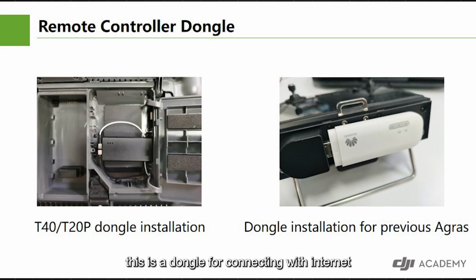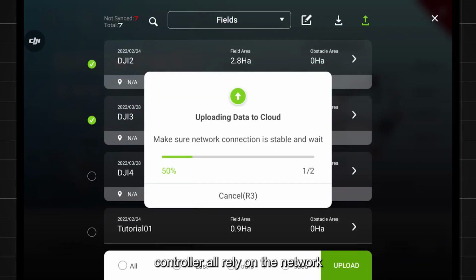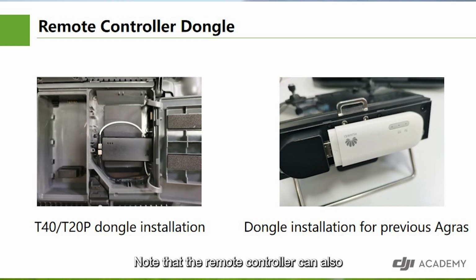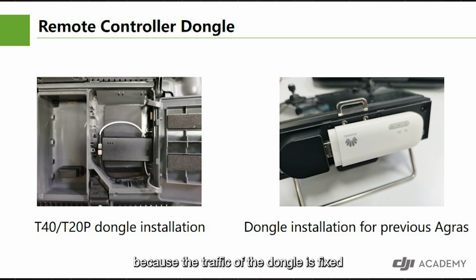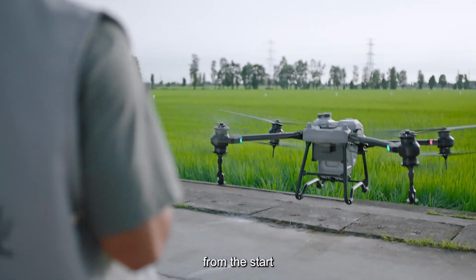This is a dongle for connecting with internet after inserting a SIM card. It should be noted that the field download, upload, and the upload of operating tasks in the remote controller all rely on the network. Note that the remote controller can also be connected to the internet by Wi-Fi. Because the traffic of the dongle is fixed, we can use Wi-Fi when upgrading firmware, uploading and downloading a batch of fields or tasks.